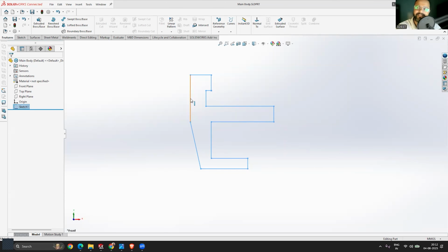And it's important inside SolidWorks, like if you want to convert any sketch entities to 3D, your profile should be closed. It's important, right? Always remember this. Even if it has 0.00001 millimeter of opening, that will not be considered as a closed sketch. So it's very important that you keep your sketch 100% closed. Then only that will start acting as a profile if you want to convert anything to 3D, right?